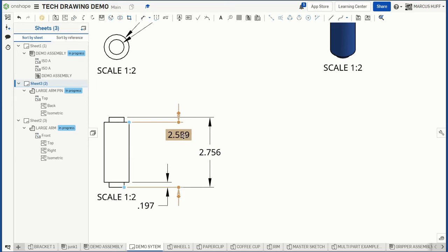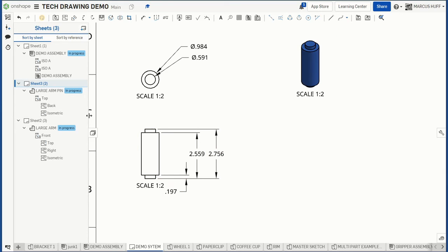I'm going to hit escape. I want this number to be in the center. So normally how you do this, you go from the smallest measurement to the largest measurement, so that makes it tidy. However, for the purposes of our drawings, if you just did the overall height, that would be fine. So this measurement by itself would be plenty if you just did that. Don't do both, okay? So I'm going to hit escape and undo that last one. Don't show the same dimension more than once. That's bad form. I would rather you have just a few, because really you're not going to machine these.